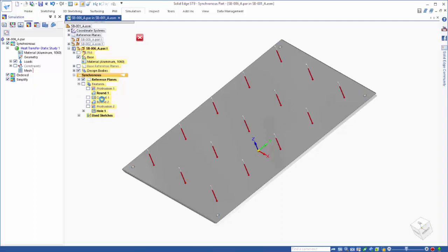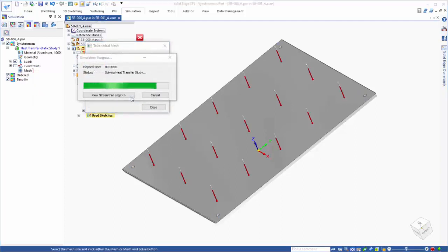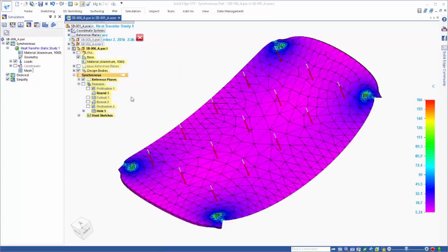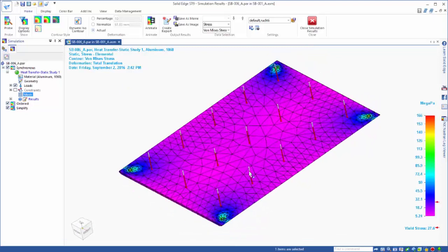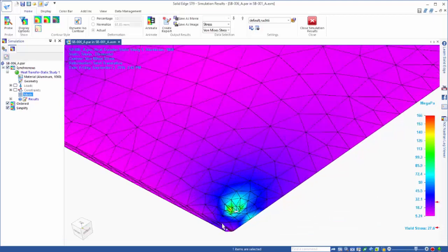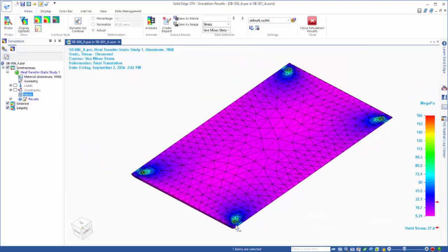Using mixed studies like this is another way in which Solid Edge helps to ensure that our designs are not only built correctly, but that they'll work as intended when produced. As we look at the results, the lid seems to have a large amount of deformation taking place. Not to worry, this is Solid Edge simulation showing you an exaggerated view of how the part will react. Clicking on the actual deformation, we can see that heavy stresses are placed on our holes, as we expected. Additionally, we can also see that the resultant stresses are well over the yield stress of our current aluminum material. Good thing we ran an analysis, because it looks like it's time to make some changes.